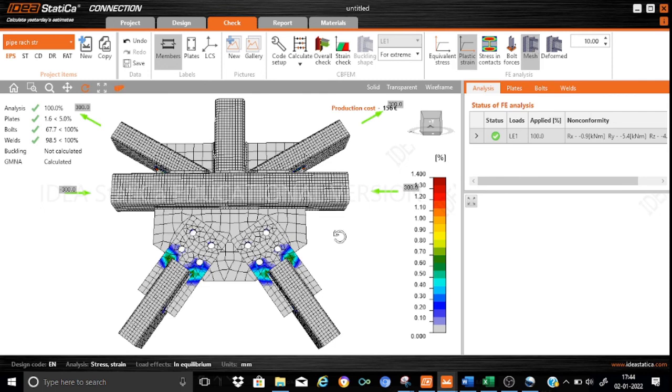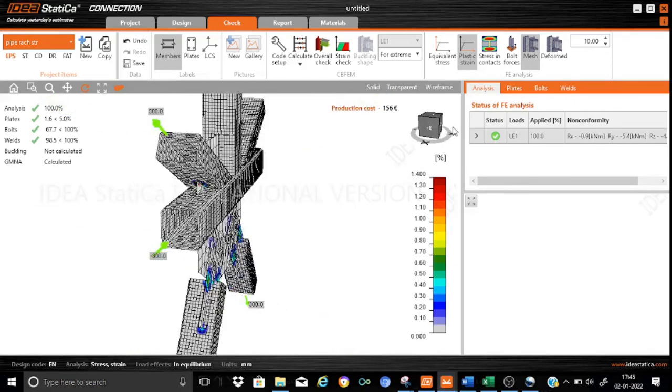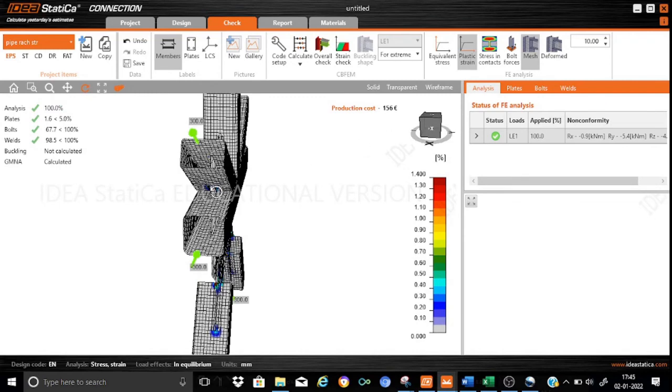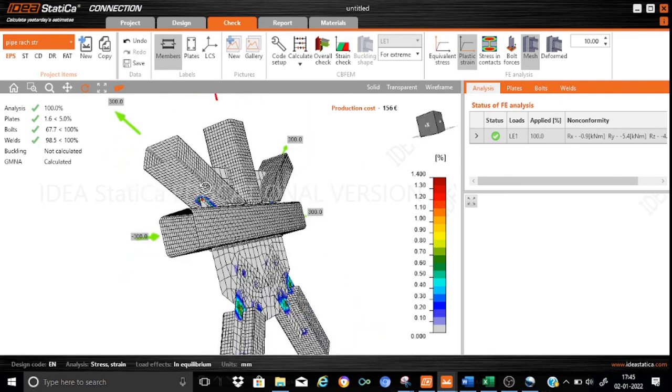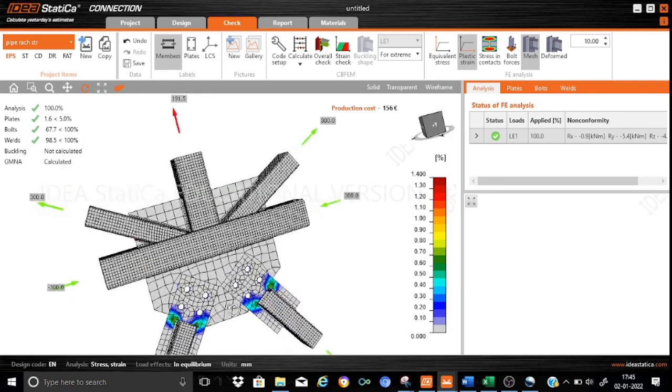So that we'll come to know what the components are. Look here, we'll find the various regions where the plastic strains are accumulated. That is just the connectivity, where this particular plate is connected to the stiffening plate, at these locations. If we look at the other locations, you will find there is some concentration of the strains near the diagonal members connection. These are all on the member itself, and here it is on the plate, what we call the connecting plate.